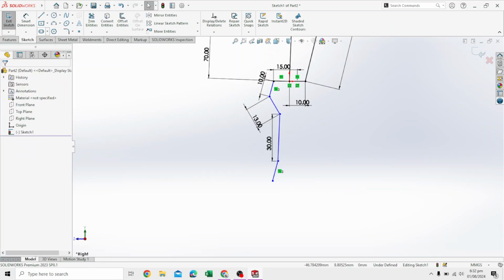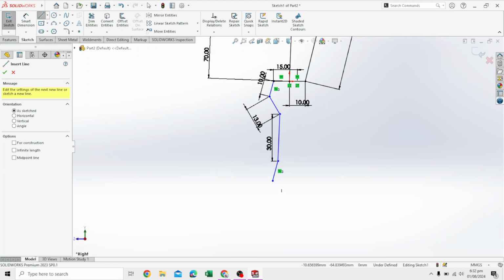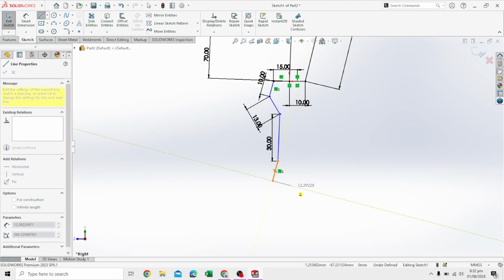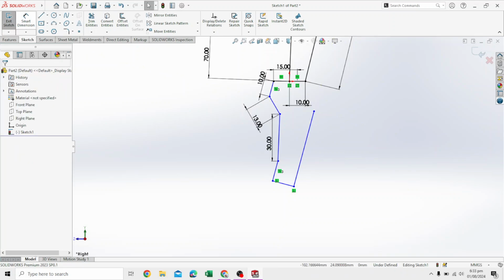It turned into the curve feature, and from here draw a perpendicular, about perpendicular, and then we will draw a straight vertical which will also be perpendicular to this, and it will be 50 millimeters long, and we can just eyeball it and then give it dimensions afterwards.